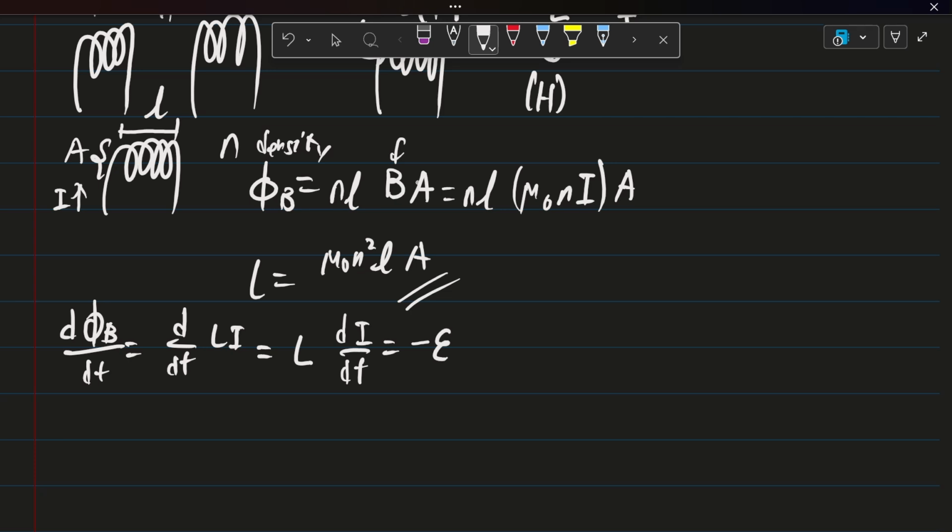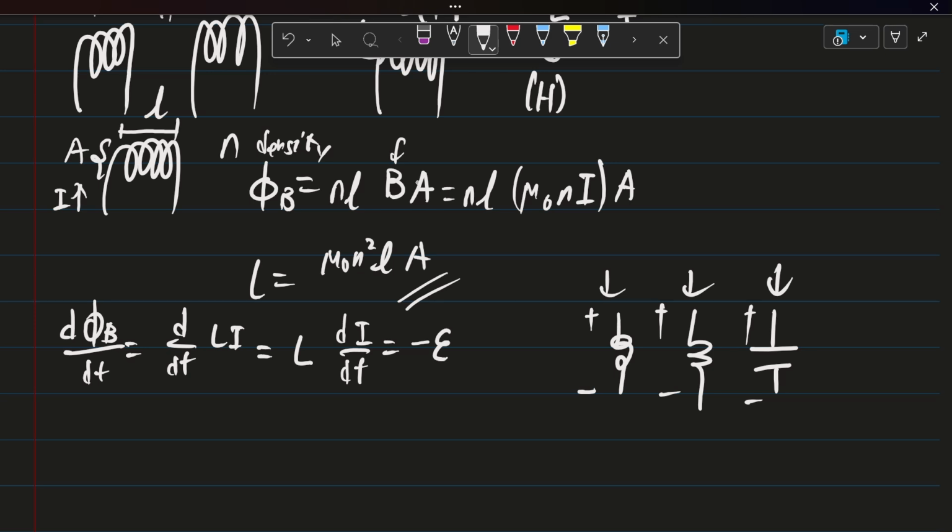But sometimes the positive and the negative terminal could get mixed up multiple times. So it really depends on your reference point and how you solve circuits. A general rule of thumb for me is by actually doing this. So this is an inductor, this is a resistor, and then a capacitor. The way that I would define the voltage difference would be from positive to negative for each, something like this, and then there's current passing through the positive terminal.